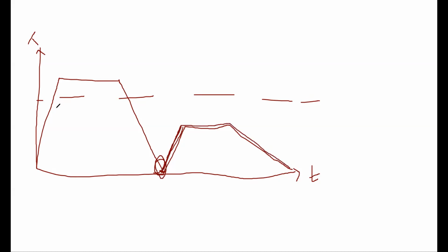What is this temperature line? You don't need to note it down, it is called the eutectoid temperature line, right? So you have to heat the metal a second time below this temperature line. So you are cooling down, then again you have to heat the metal. So this is the tempering process, right?